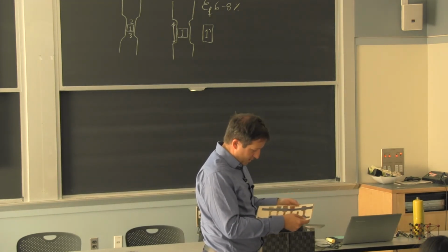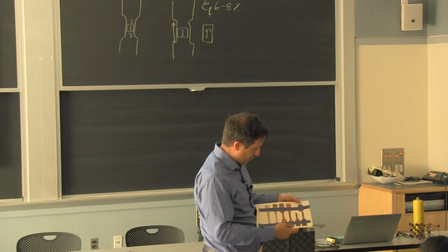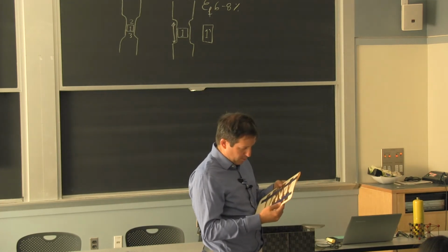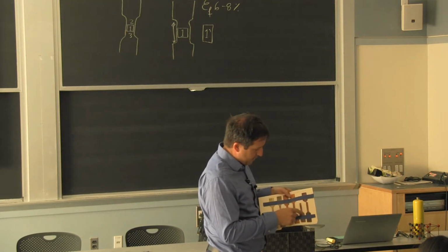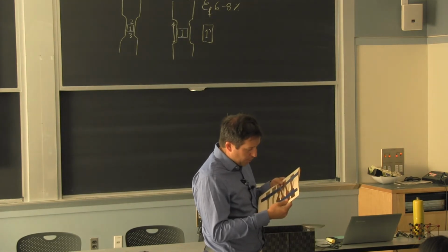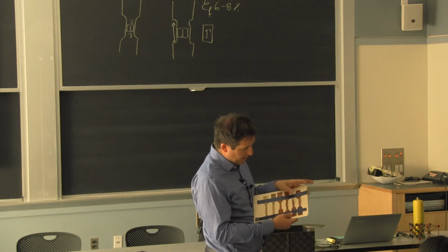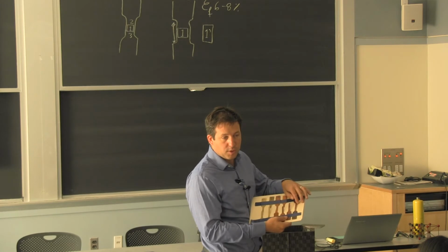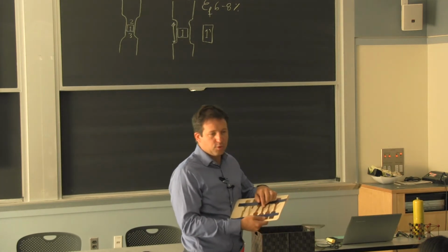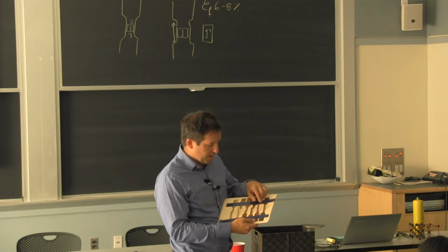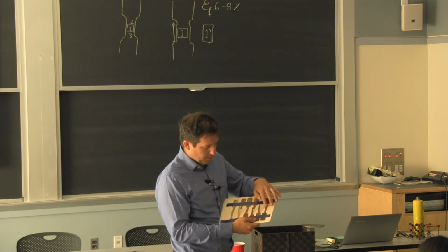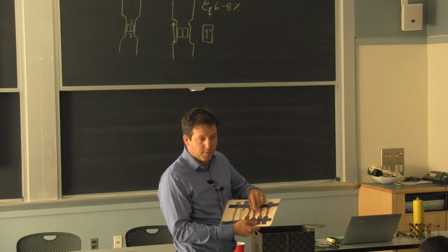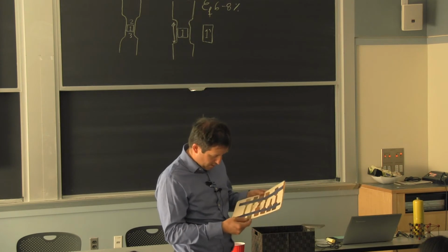And you can see that at 700, the material deformed quite a bit more than at 450. One thing that hopefully the light allows you to see, I may have to bring up a little more light: the middle sample, the one at 600, you can see what we call an orange peel effect. So you'll see an effect of the grains here that you don't see at all at the lower temperature treatment. And you see it a little bit at the higher temperature, but it's not quite as big. So when you think about it, it's not linear, right? No grains visible, a lot of grains, and at the higher temperature back to some effect of grain, but not as big. So there is a peak there.